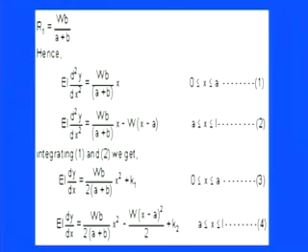So now you see here, first of all, the reactions R1 and R2 are there, and since they are coming from both of the supporting points due to the load condition, R1 can be easily calculated by putting the moment equation and the force equation equal to 0. Under the action of this load the beam is in a symmetrical way, so R1 can be easily calculated with that.